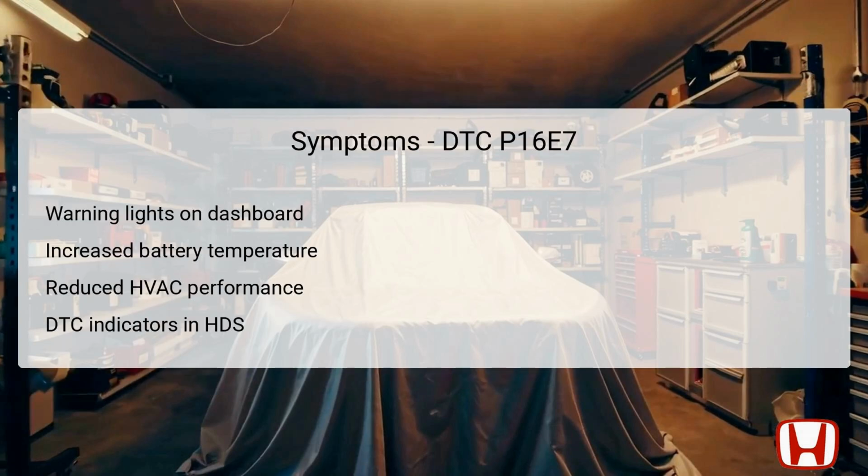Symptoms of DTC P16E7 can manifest in several noticeable ways. Drivers may observe warning lights illuminated on the dashboard, indicating an underlying problem with the battery ventilation system or the vehicle's electrical systems. An increase in battery temperature can also be a key symptom, suggesting that the battery blower is not functioning correctly and may jeopardize the battery's integrity.